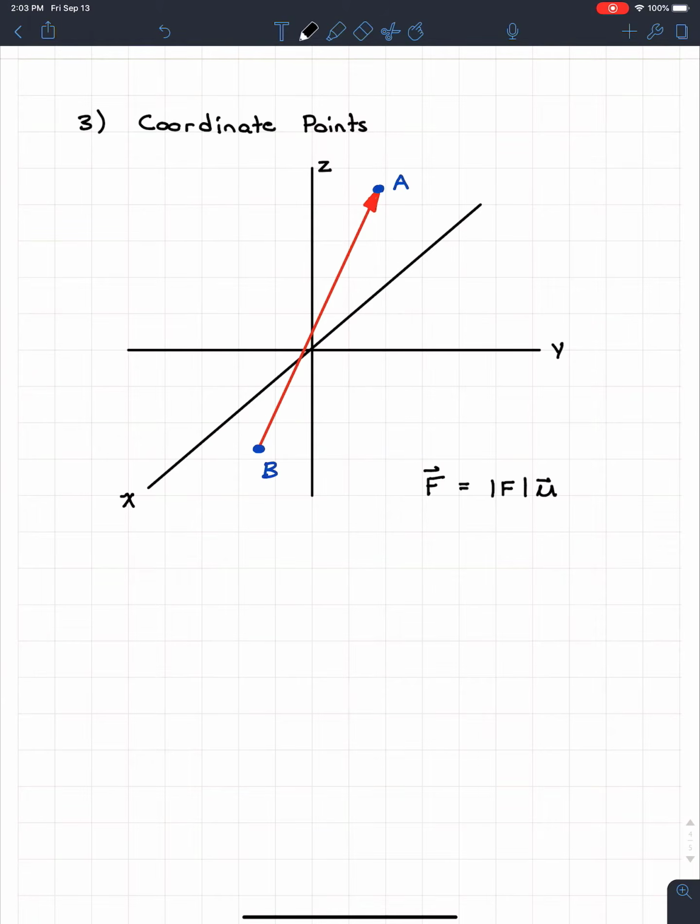The magnitude of the force, right here, in these questions, well, that's really your unknown. Equilibrium is about solving for the magnitude of forces. Usually you're not also going to get the force vector in Cartesian vector notation, so this will also be your unknown, because you can't solve for it because you don't know the magnitude. So now you're going to start saying, okay, well, two unknowns, why are we really doing this? And it's because of that unit vector at the end, which I'll highlight right here. It'll become very apparent why we're trying to find that.